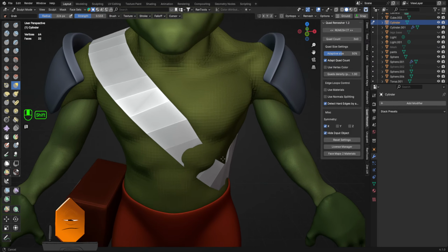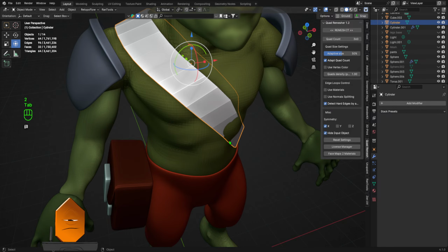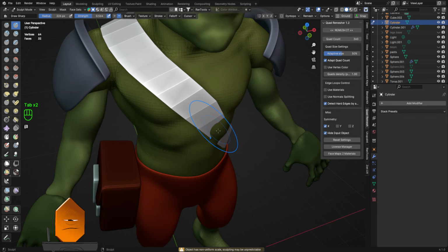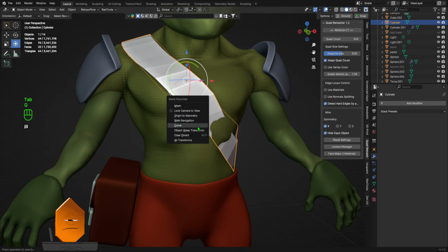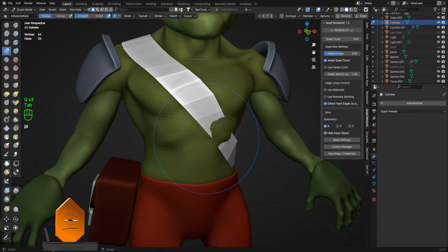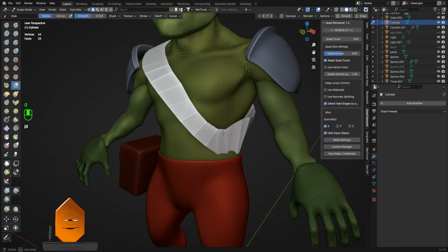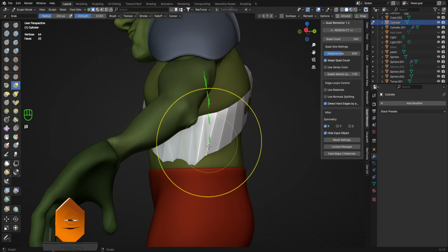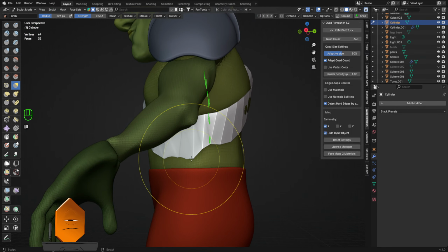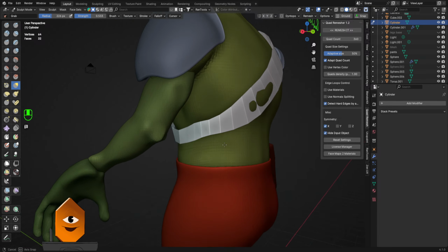Let's do this here. Back to sculpt mode. G, I'm just gonna pull it out. 3, I can inflate it. Select this, all transforms, origin to geometry. G. There we go. It's got absolutely borked here somehow. Smooth it out.